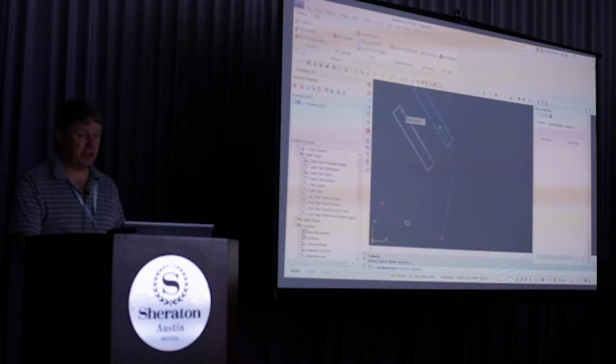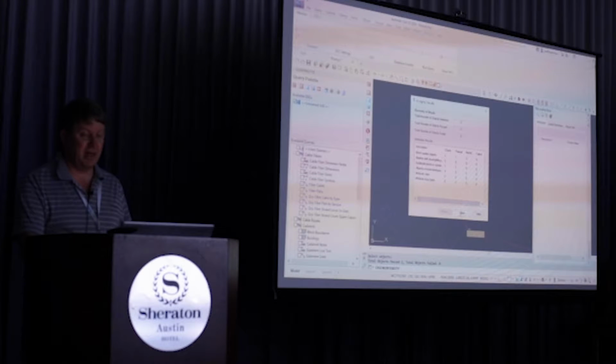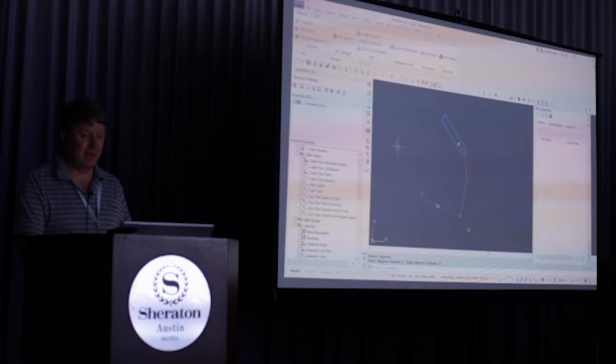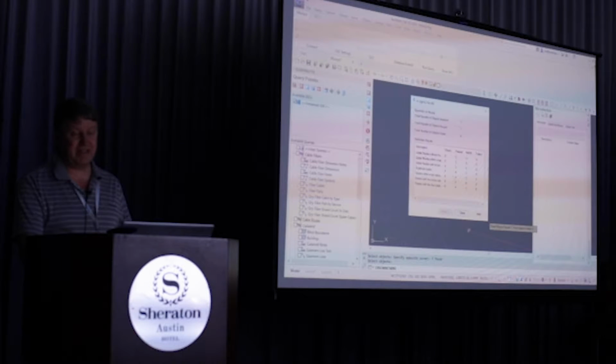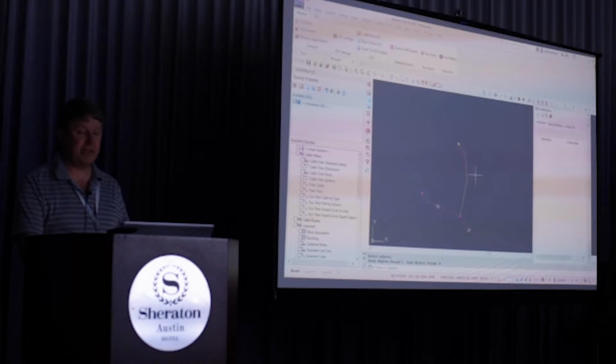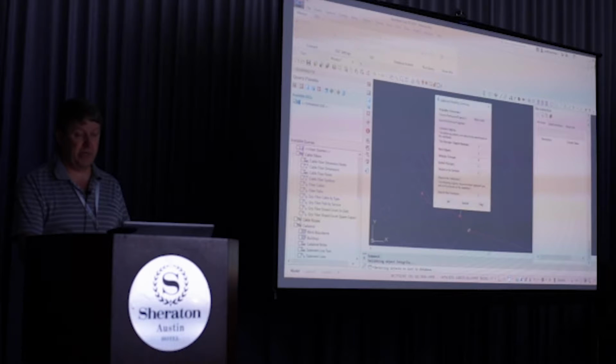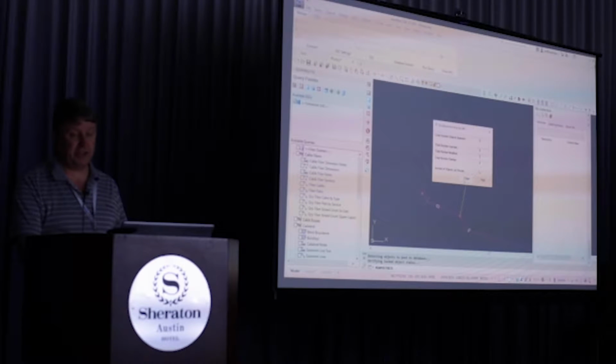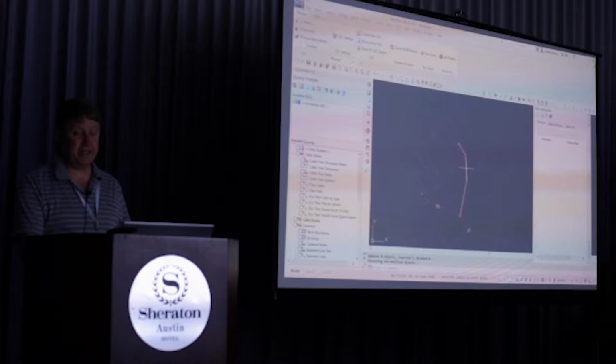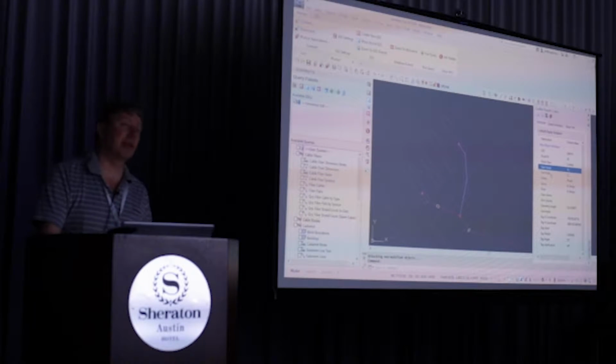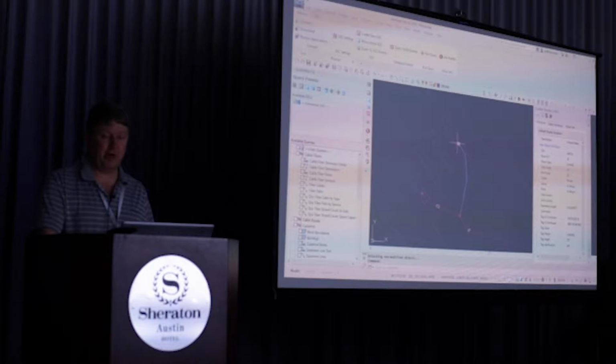So I'll just run an integrity check, and what that will do is some calculations, and you can see the colors that tell you whether it's been fixed. And so now that will post to the database, and that's now in the database, and it automatically built our connectivity for us. So that is then from this room to that room.